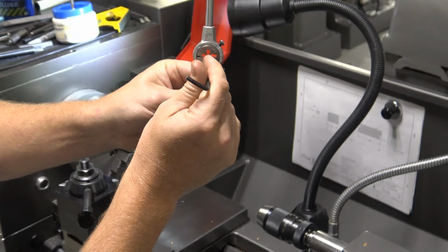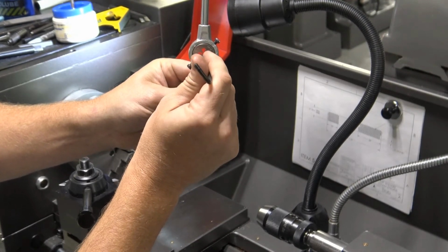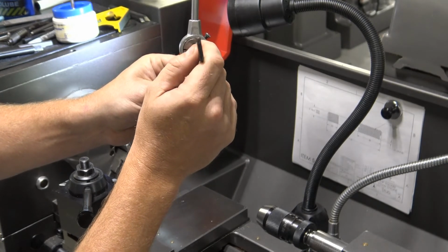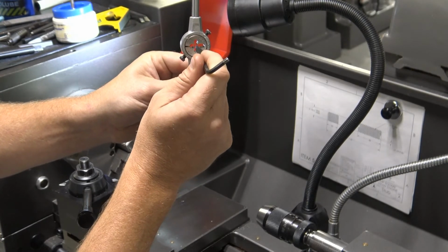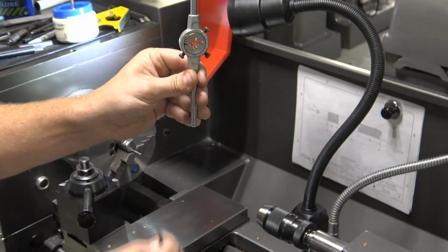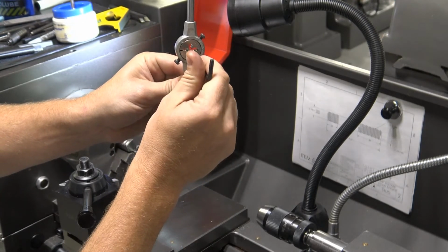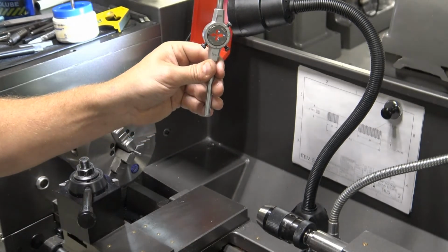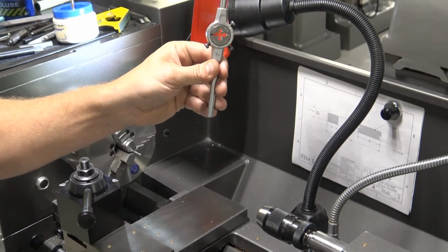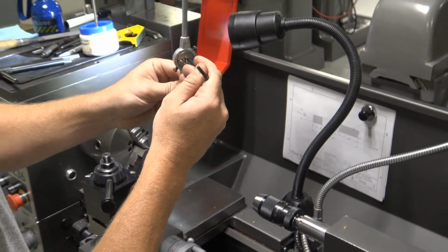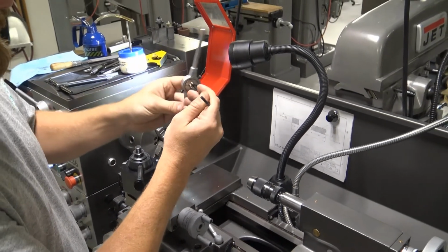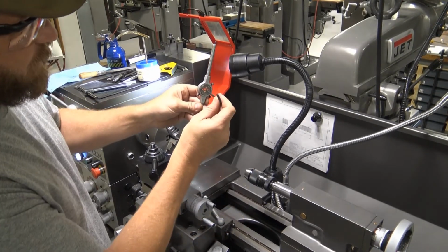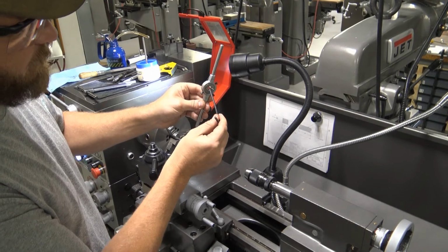I've seen people try to put it in these little holes. If you think of it looking kind of like a clover leaf, they want to put it out here on the clover leaf, all right? What we need to do is put it right in the center, okay? All these little holes around the side are just a place for the chips to go, all right? So don't stick the material in there and start turning it like this. You won't be cutting anything. All right, so make sure you line it right up in the dead center.